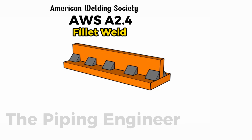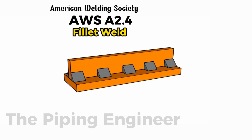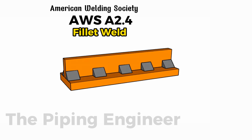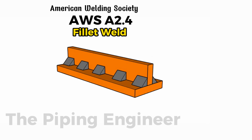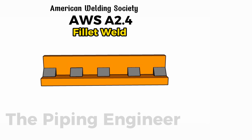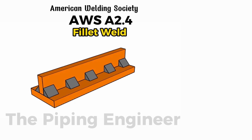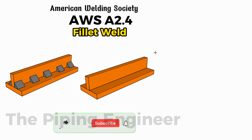Sometimes you'll run into what we call intermittent or stitched welds. Instead of running a solid bead all the way down the joint, you weld for a specific length, skip a section, leave a gap, and then weld that exact same length again. You just keep repeating that pattern evenly all the way down the joint until you hit the end. The cool thing is, all these dimensions are spelled right out on the weld symbol.